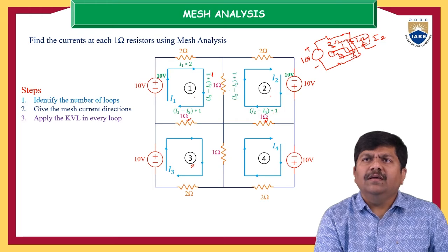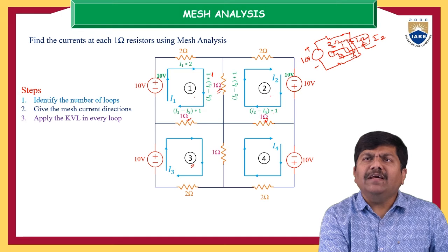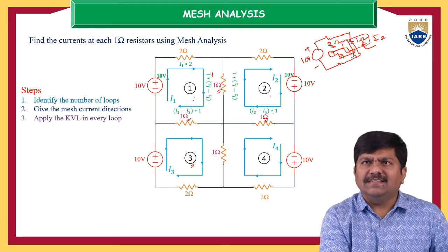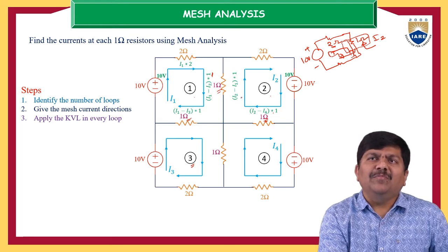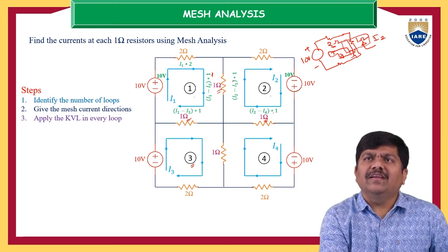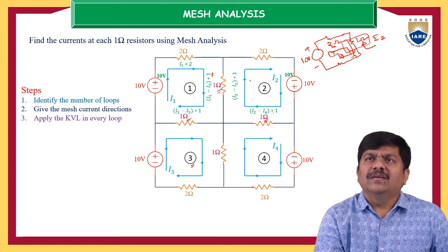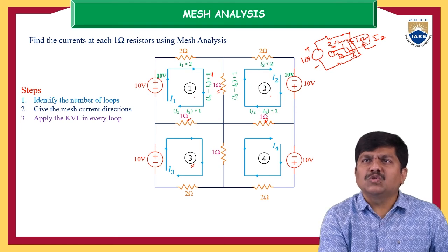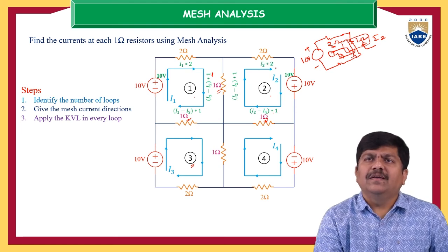So second one, here you see the beauty of this 1 ohm resistance. Whenever we are applying the mesh analysis or KVL for this loop 1, we have given the priority for I1, and whenever, across the same 1 ohm resistance, we are attempting to find out the drop across this 1 ohm, that is I2 minus I1 into again the resistance value. So the last one is across 2 ohm, that is I2 into 2.